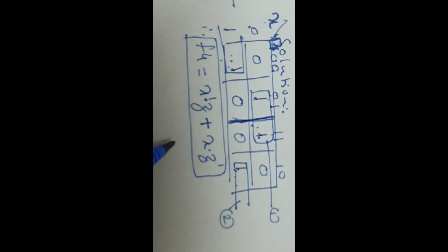These two are called as prime implicants. Are they essential prime implicants? How to know this? Because there are two groups, only they can be made, no other group. And what prime implicant we have found for each group, they are included in the simplified solution, final solution for the given Boolean function.